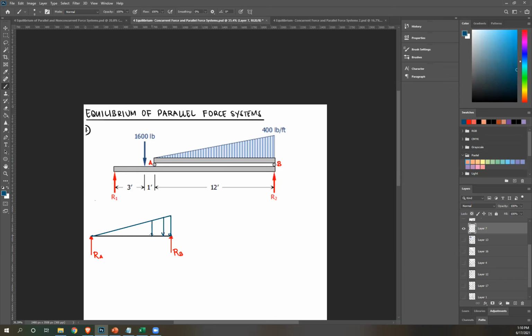Okay, these are downward. And then here, let's draw as well for the bottom beam. So we have reactions here, upward, upward, and then since there's rollers here, there will also be reactions here. Okay, now if you decided this is upward, moving on to the next free body diagram is the opposite. So this will now be downward. Okay, and if this is upward, this is also downward. And then we have an external force over here, right?